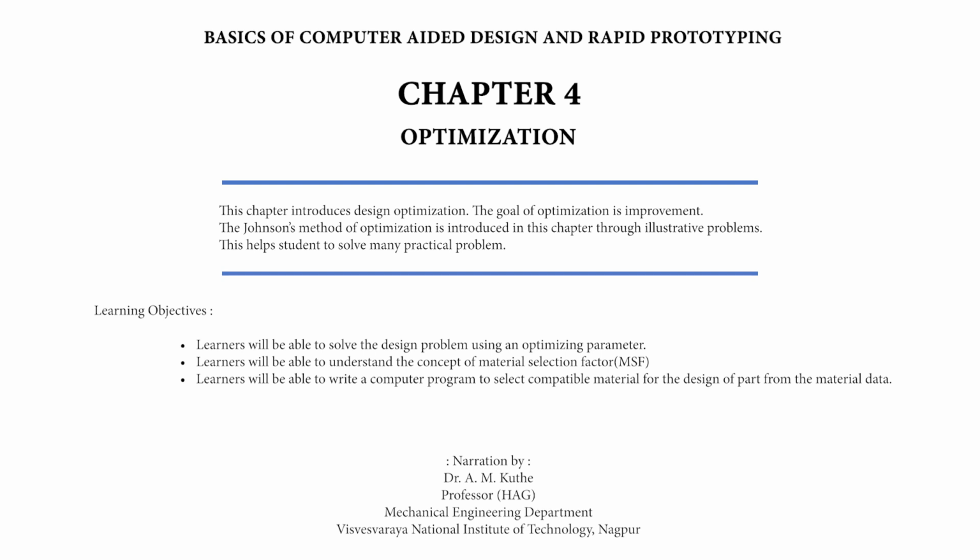If the number of free variables is greater than or equal to the number of subsidiary design equations, then the problem is called a normal specification problem. If the number of free variables is less than the number of subsidiary design equations, then the problem is called a redundant specification problem. An incompatible specification problem is a special case of redundant specification problem. Para 4.2.2 Final formulation. In the final formulation, a solution to the design problem is obtained.